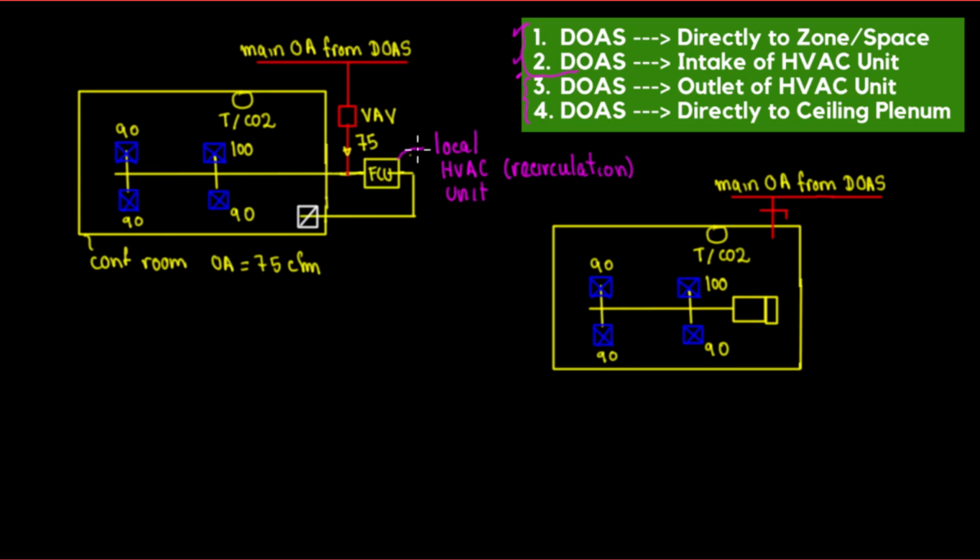However, this is very interesting because based on the balancing, let's think about this. What is the SA, the supply air, how much is it? If you add this 100, 90, 90, 90, that's going to give you 370 CFM, okay? And why am I doing this math? Because we need to know how much CFM I'm going to size this grille for.